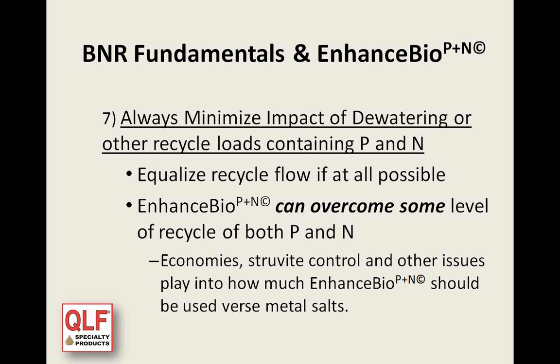The last one is minimizing the impact of dewatering, thickening, or other recycle loads. And remember, those loads contain not only phosphorus, but they also contain nitrogen. A good way to take care of that, if at all possible, is to equalize that recycle flow.